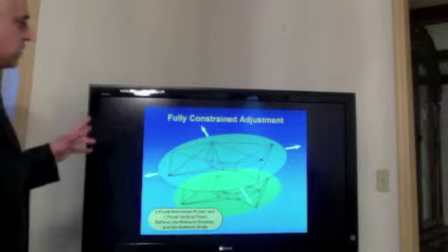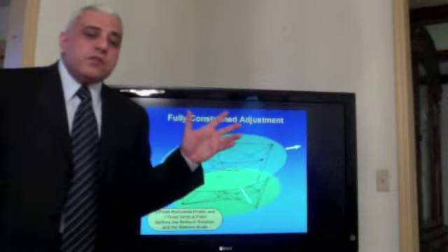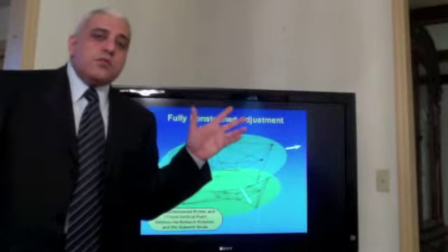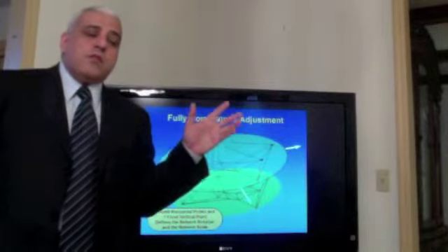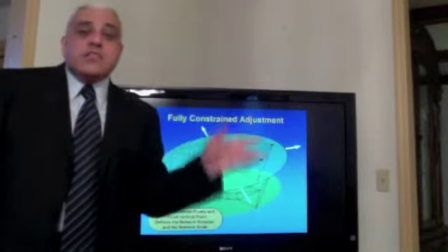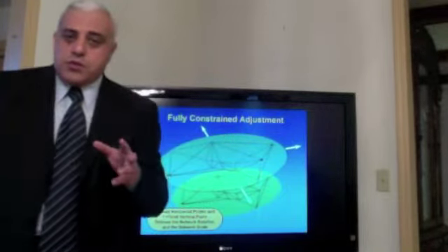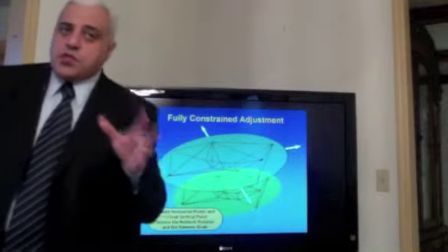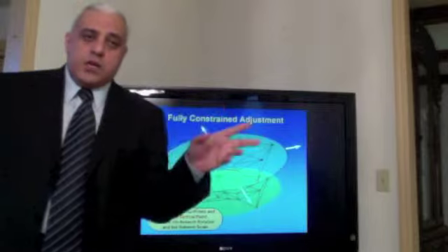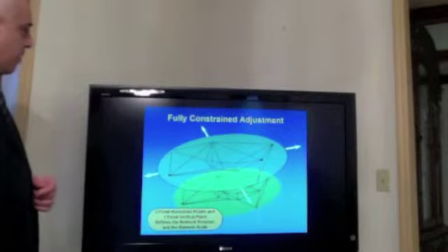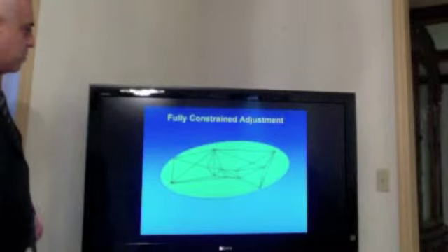So we can see that we should have 3 of the 3D points, which have the x, y, and z as well. So we can use 3 of them, giving us 9 equations. So we use 7, which is the necessary observation, and the other 2 will be a check for final evaluation and used as redundant observation.